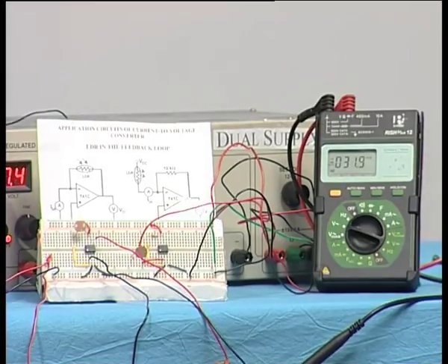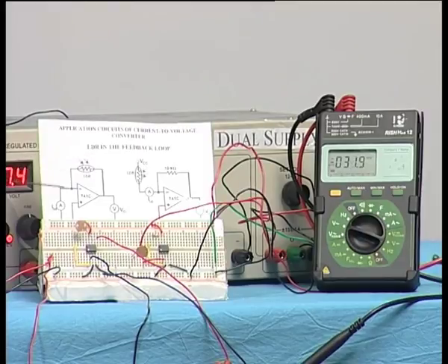There is also another way to get the circuit, and that is, instead of putting it in the feedback, I am using the LDR itself as a current source. So that circuit is shown in the next part of the breadboard. You see another circuit here. You have the LDR now connected to some 5 volt supply. So the 5 volt supply with the LDR becomes a current source in effect, and that is connected at the